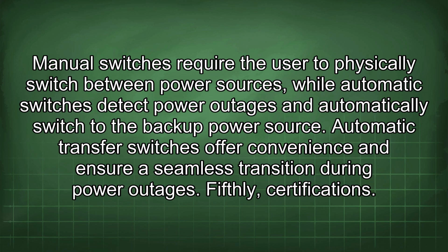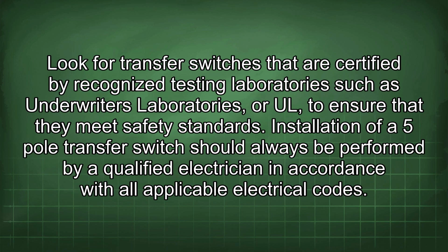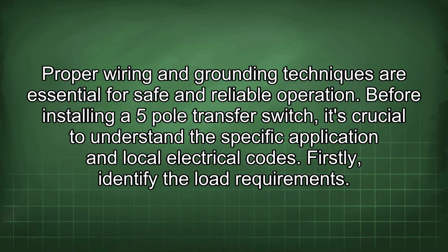Fifthly, certifications. Look for transfer switches that are certified by recognized testing laboratories such as Underwriters Laboratories or UL to ensure that they meet safety standards. Installation of a 5-pole transfer switch should always be performed by a qualified electrician in accordance with all applicable electrical codes. Proper wiring and grounding techniques are essential for safe and reliable operation.